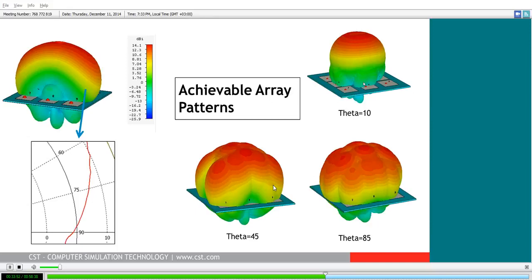As you get up to theta equals 45 degrees, though, we start to see some interesting trends in the steered array. In particular, we get some nulls here on the sides, the horizontal sides of the array where we have some blindness. This is something that we could look at tackling potentially by adding a token amount of diversity to our antenna design, perhaps by rotating a secondary array within the device. It's also worth noting when we're looking at these swept patterns that clearly this is a hemispherical array. These square patch antennas operate off of a ground plane.